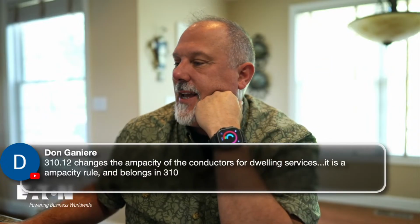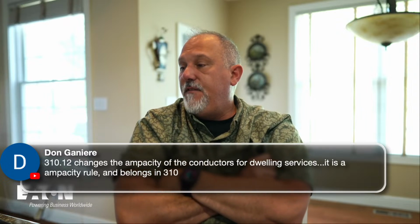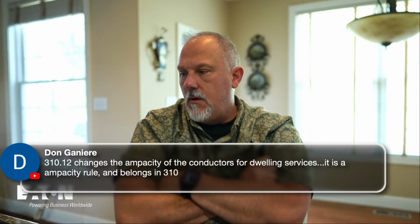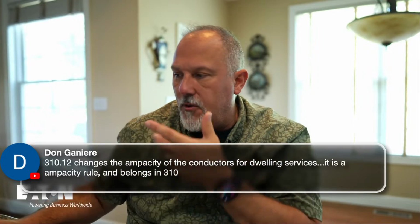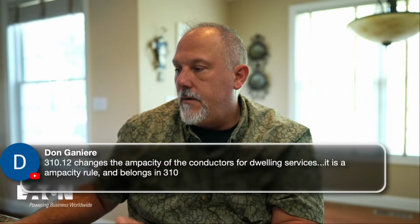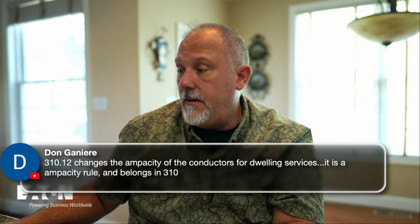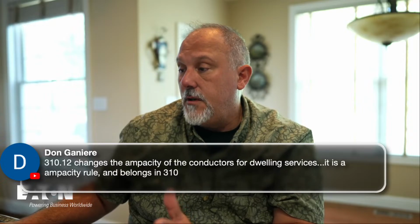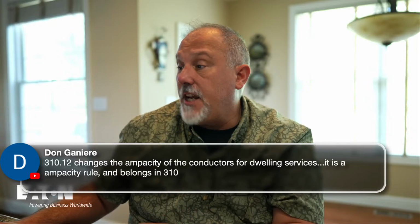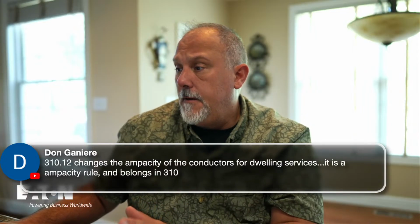It's a Wired Wednesday. So this says single-phase dwelling services and feeders. So Table 310.12 is not an ampacity value. It tells you a conductor size and the service rating. It tells you the conductor to use. It doesn't change the ampacity of a conductor. I don't believe it does.